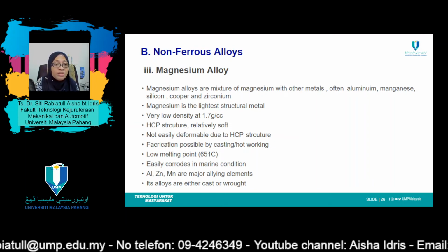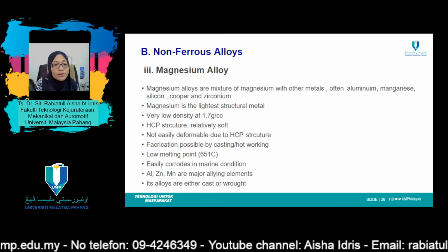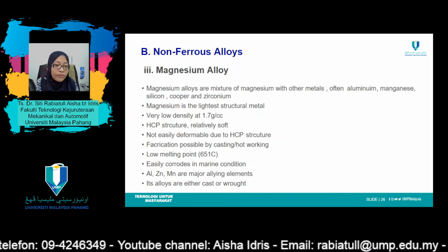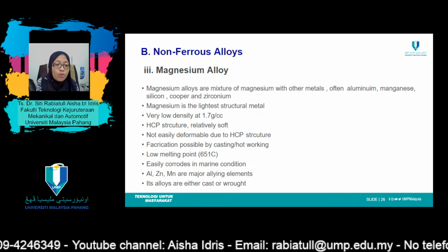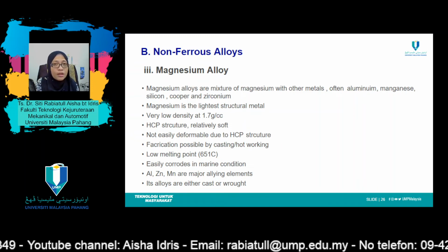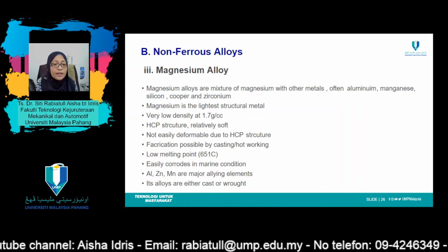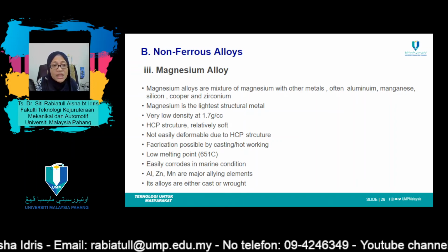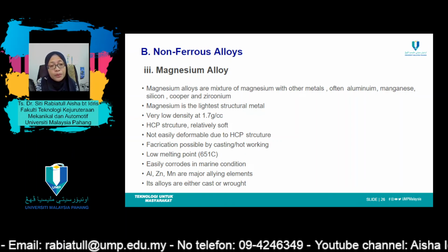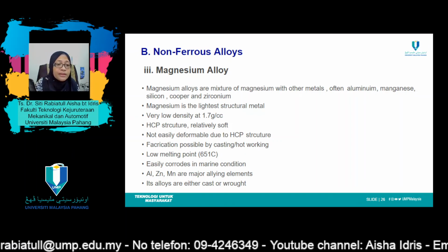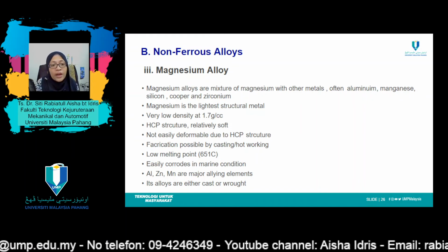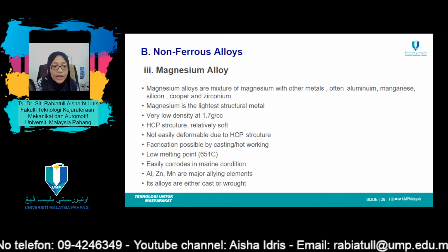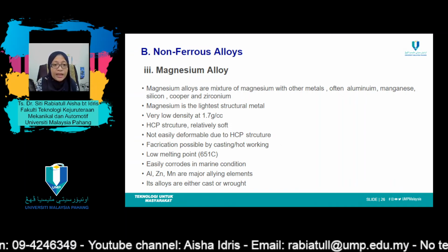moderately low melting temperature. Chemically, magnesium alloys are relatively unstable and especially susceptible to corrosion in marine environments. On the other hand, corrosion or oxidation resistance is reasonably good in a normal atmosphere. It is believed that this behavior is due to impurities rather than being an inherent characteristic of magnesium alloys. Fine magnesium powder ignites easily when heated in air. Consequently, care should be exercised when handling it in this kind of state.